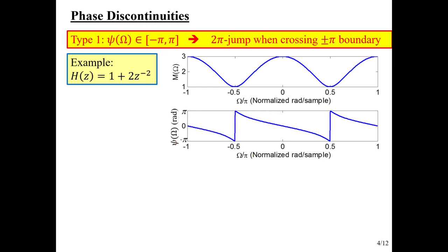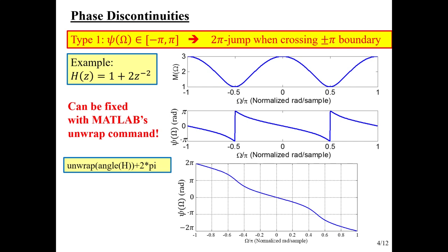And MATLAB says, I can't represent an angle down here, so it represents it up here. So there's that discontinuity. I show it in the plot with a vertical line there, but there's really no vertical line. It just comes down to here and then discontinuously jumps up. MATLAB just draws lines between successive points, so that's why it looks like that.